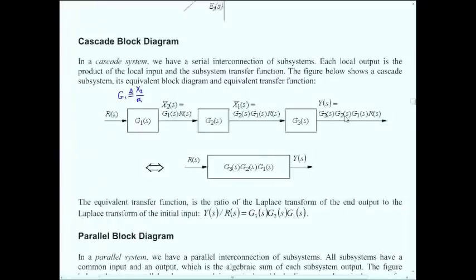A simple multiplication of transfer functions is involved when you've got blocks in series, called cascade. So the overall transfer function is just the multiplication of all the transfer functions together. And that is one of the key things about the Laplace domain that's really useful for control. It enables us to simplify blocks in series by pure multiplication.